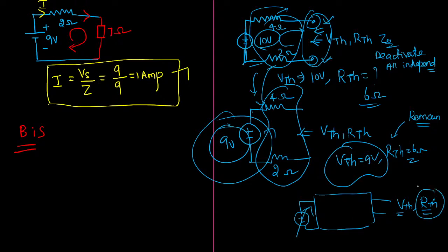But Thevenin resistance simply depends on the configuration of the internal circuit, how the resistors are connected, whether in series or parallel, what type of connection it is. Based on that only, Thevenin resistance will be different. It does not depend on the active element present at the input port. Conclusion is over. Now apply the same logic to our circuit.